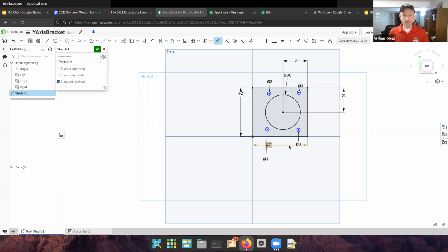I can kind of drag them around. I escaped out of the constraint tool. See if I can drag these pieces here. There we are. That little hand appears. And then I can sort of clean it up so that we can see all the constraints at the same time without getting things too much out of order.